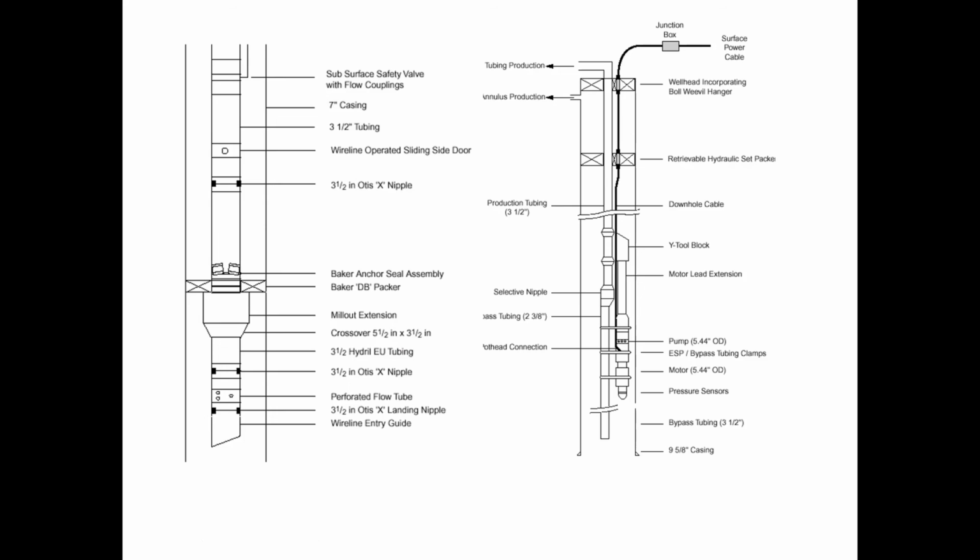That heat from the motor can be used for heating up the fluid, therefore reducing the viscosity and density of the fluid. So it will help the fluid to be pumped. If it was the other way around, and the level of fluid was below this section, then the pump would have burned. And also it wouldn't help in pumping the fluid.